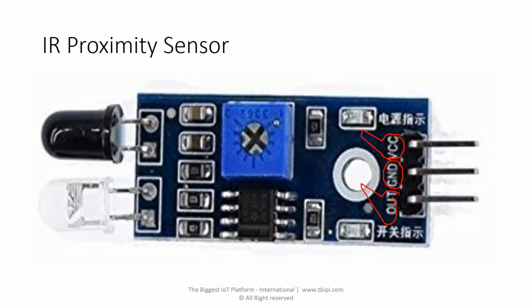Okay, so do one thing on Arduino. You have a 5-volt pin. Connect VCC to the 5-volt pin and ground to ground. On Arduino you have 5-volt and ground pins, and you connect VCC to 5-volt and ground to ground. If you do that, that's just two connections, only two wires. Okay, I'm also going to show you the wires.